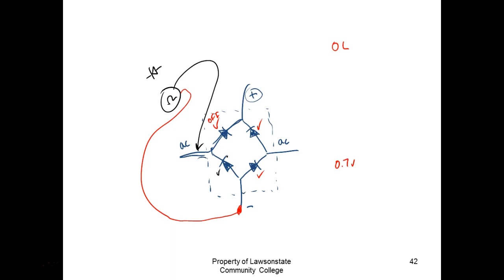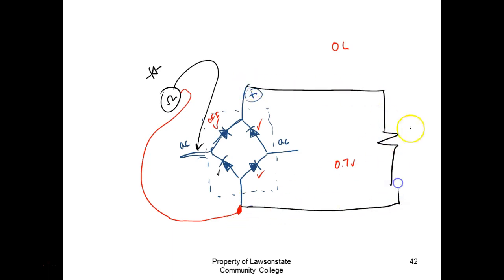If it checks good in circuit, you assume it's good. If it checks bad in circuit, then you're going to have to isolate it. Y'all understand that? Because these guys are power supplies, and power supplies are definitely connected in parallel with loads, right? So if I took this plus and minus out here and hooked it up to a 100 ohm resistor, then we got problems, right? It's probably going to measure 100 ohms both ways, even when you reverse bias one of the diodes.